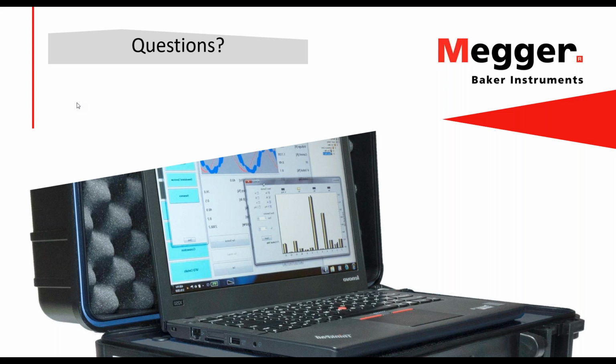If I have a brand new plant, brand new motors, then I would probably choose the dynamic testing, because I'm making the assumption there that my motors are starting out good, and I want to assess the environment that those motors live in, and that would give me warnings such as voltage imbalance or distortion or overloading type answers. I know what's going on with the motors, and as it ages, then I would start bringing in the static piece. Again, it kind of depends on your situation and the motors that you're wanting to test.